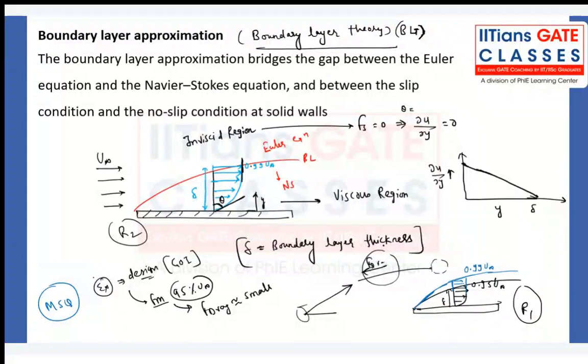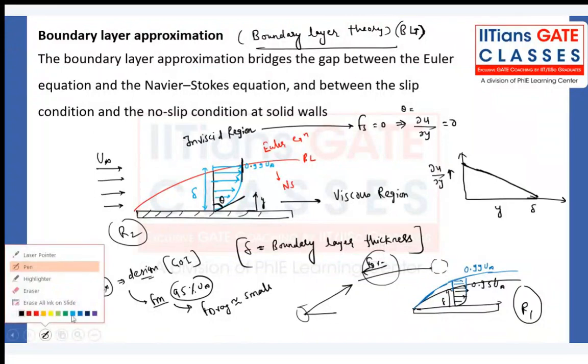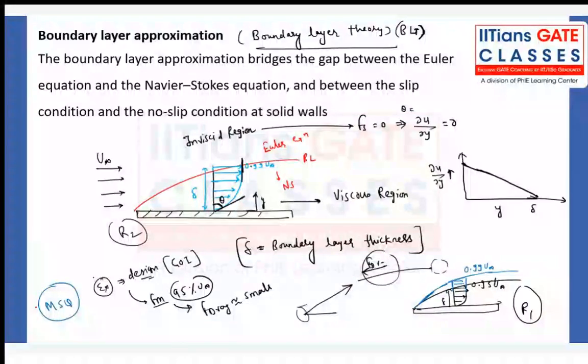The next question, when the inquiry is held regarding all this drama which happened, then definitely who will be blamed first? The engineer who designed that aircraft. Even though accuracy is not a matter at all, 99%, 95%, almost the same, still the drag force might be significant, because in calculating the drag force we are not only calculating the coefficient of drag, CD. See, what is the formula? Half CD rho A u infinity square.